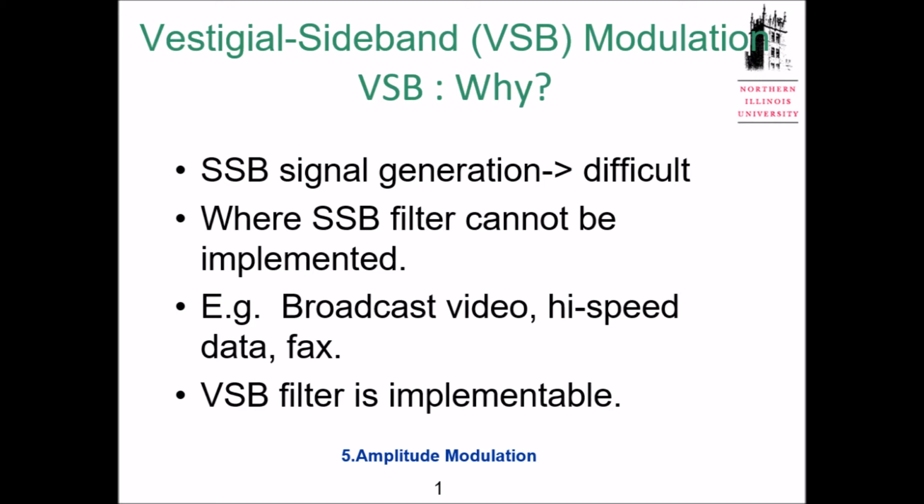If you plot square or triangle waves, the spectrum has pretty high low frequency content. The sinc function is your spectrum, so we cannot implement single sideband. There is an alternative way, vestigial sideband modulation, and the filter we use is also called a vestigial sideband filter. So let's look at what we do. Any problems, any questions so far?